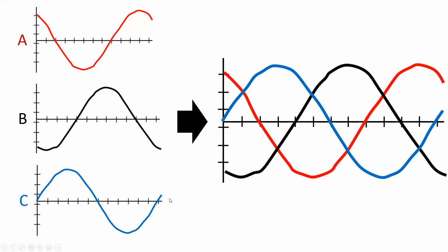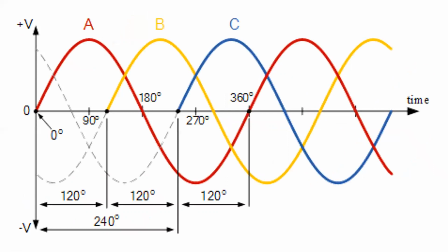They are 3 distinct individual phases that happen to be offset by 120 degrees due to their physical mount inside the stator of the generator. This is an easier graph to view and see the difference. It is a uniform separation where A, B, and C reach their peak values 120 degrees apart from one another.